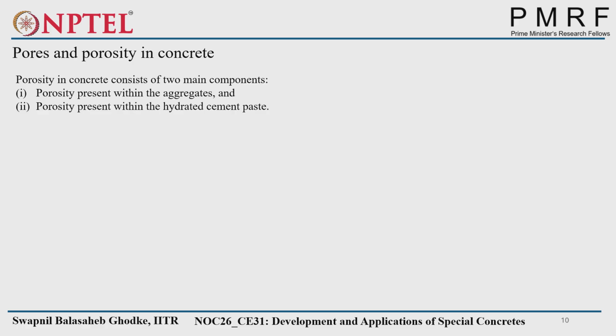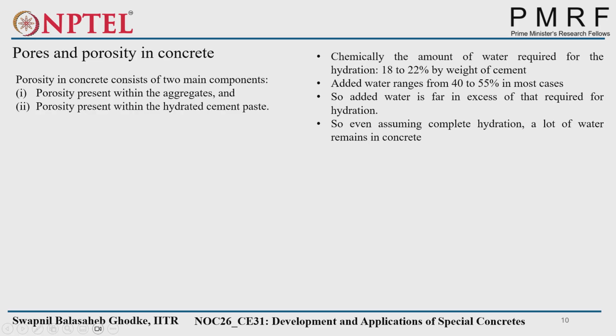So next is pores and porosity in concrete. Porosity we already saw. Maybe the aggregate will also be porous, and that will also absorb some of the water from your concrete mix. That's why most of the time it is advisable to use saturated surface dry condition aggregate, or in the design mix also we are considering the aggregate water, how much it will absorb. And another porosity will be present in the hydrated cement paste also.